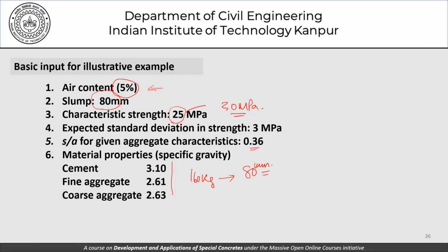As far as the strength is concerned, we may have to wait for 28 days before we know whether or not the 50% water cement ratio that we used actually yielded the 30 MPa that we thought it will. If it does not, then we may have to make an alteration in our water cement ratio itself. Those are the kind of things that we really need to be concerned about.